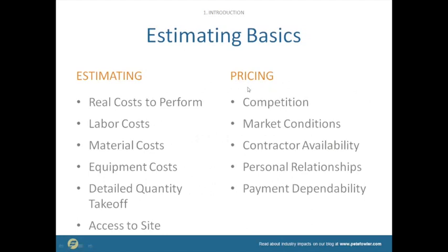So estimating versus pricing, this is a very important dynamic here. Estimating is really figuring out the cost to perform the work. What's the labor cost? What are the materials costs? What are the equipment costs? We have to do a detailed quantity takeoff if we want a really precise estimate. We need to know exactly how many square feet or cubic yards or square yards there are in this, and are there access issues? These things can cost money. But pricing has to do with things like competition and market conditions and contractor availability and personal relationships.